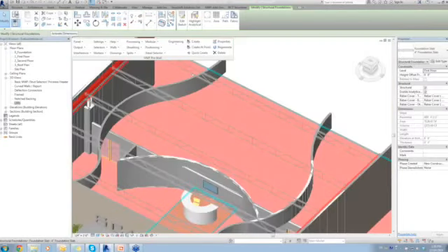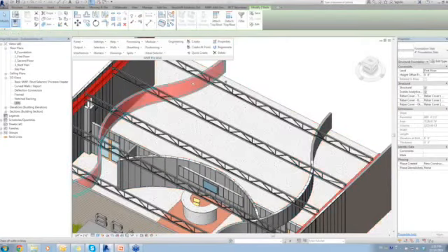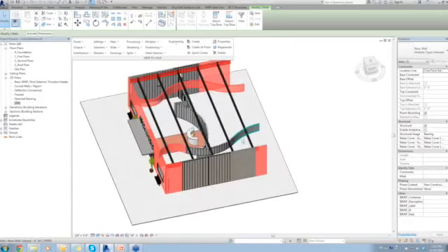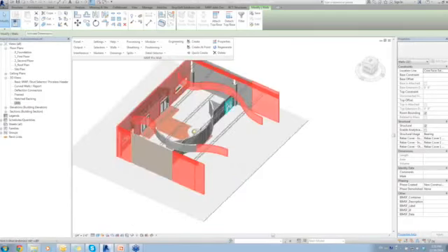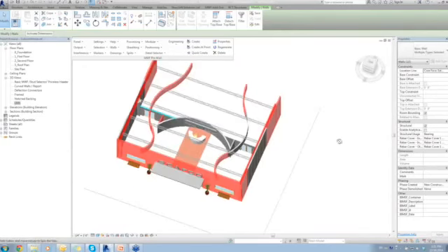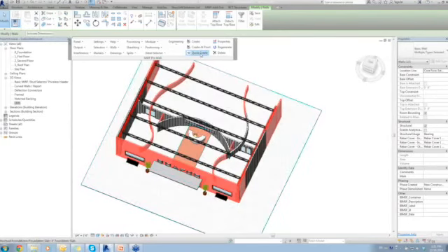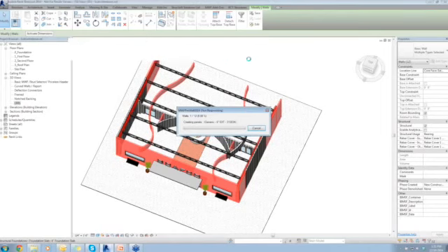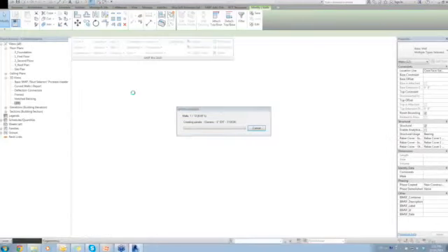And then I can now simply select all the walls in my project that are missing panels, these little guys in here too, and simply run the quick create option again to generate all of my panels, all of my studs with the SCAFCO families that we've been seeing. So right now I'm actually creating 12 panels, so it's going to take a minute.